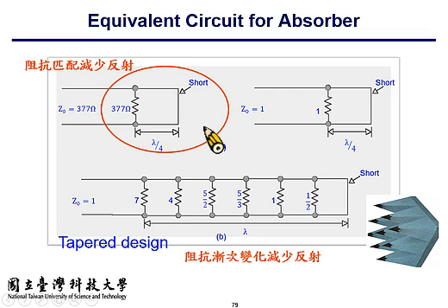Of course, the input impedance at the short is 0. What happens to the input impedance at a quarter wavelength? It's infinity. It's like an open. Okay, because of the total standing wave, here you have 0 voltage, here you have 0 current, so the impedance here goes to infinity. So it looks like an open with a quarter wavelength spacing.